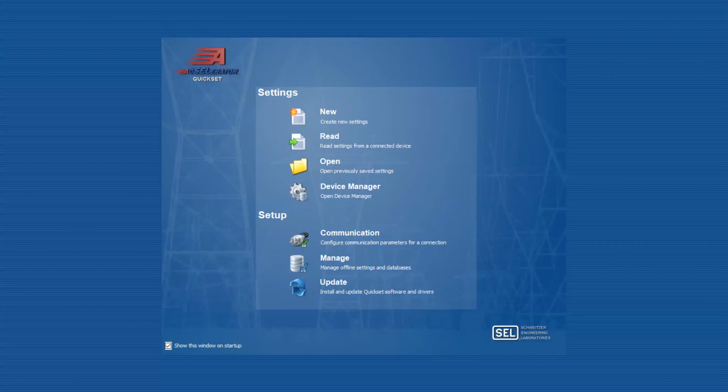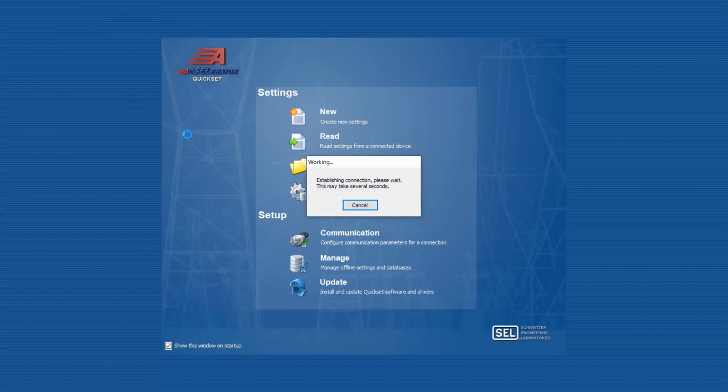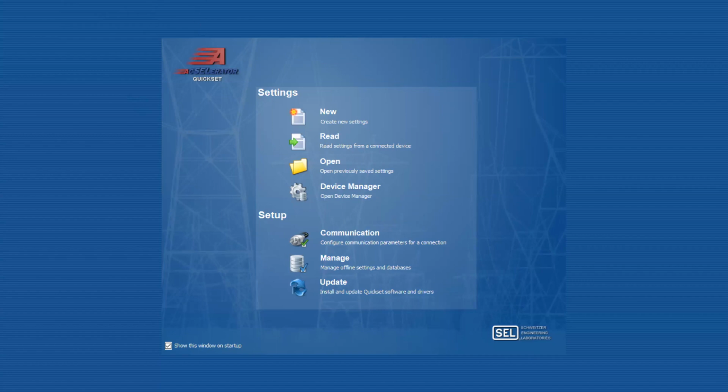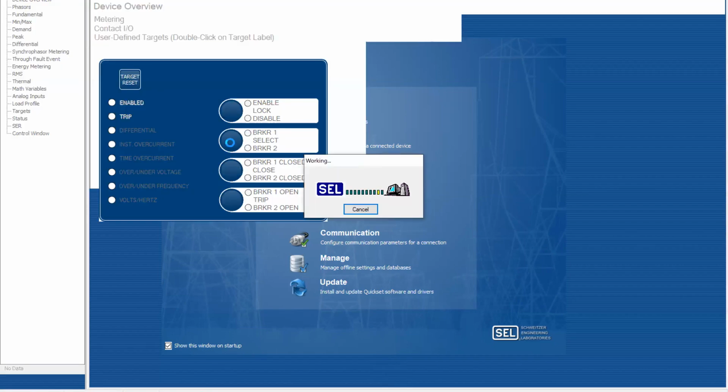So why do we need to run something called a stabilization test? The reason I do this test is that we are checking the metering on the relay when I inject normal current, normal load condition current, to the relay, which means there is no differential condition. The currents are balanced on both the sides. And I need to make sure that what I'm injecting is what I'm reading on the relay. Okay, so it's opening up the HMI for your Schweitzer relay so that we can look at the metering data.